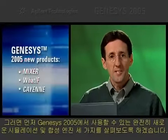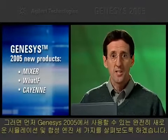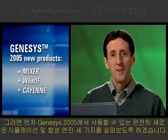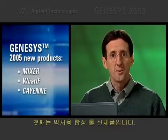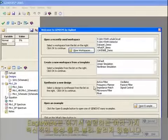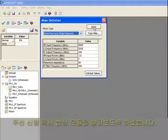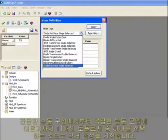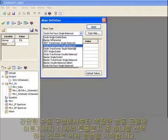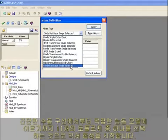But first, let's take a look at three significant new simulation and synthesis engines in Genesys 2005. The first is a new synthesis tool for mixers. Eagleware is well known for its many innovative synthesis tools shown here. I'll select the new mixer synthesis module. You start a mixer synthesis by choosing one of 11 topologies ranging from simple passive configurations to complex active models.